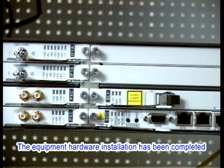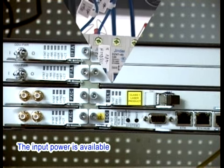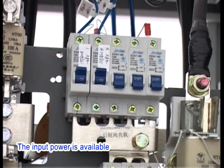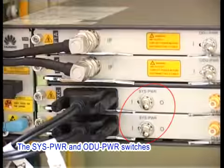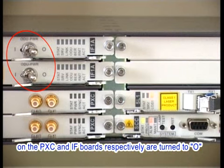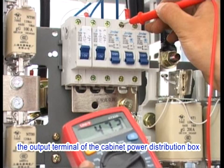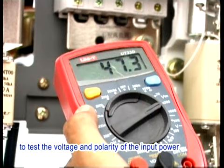1. The equipment hardware installation has been completed and has passed the installation check. 2. The input power is available. 3. The input power has been turned off. 4. The system power and ODU power switches on the PXC and IF boards respectively are turned to O, which means off. Connect a multimeter at the input power supply, for example, the output terminal of the cabinet power distribution box, to test the voltage and polarity of the input power.